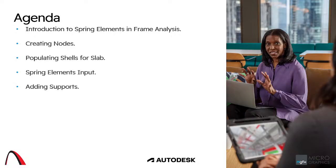And then from there, we will add in supports just to provide lateral stability in our model, because we know if you try and analyze a model that is not stable at all, the program will definitely flag it and actually tell you that you need to provide stability in your model.